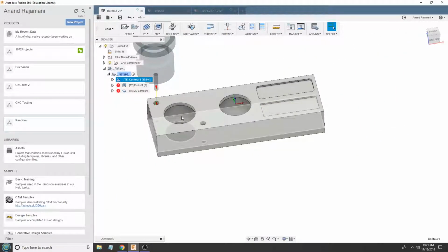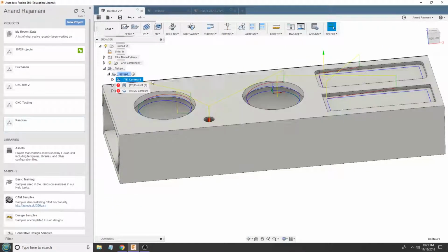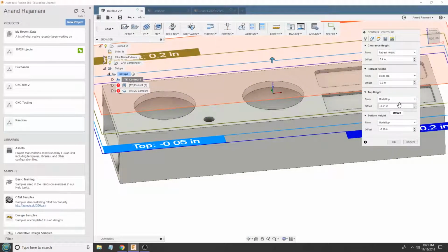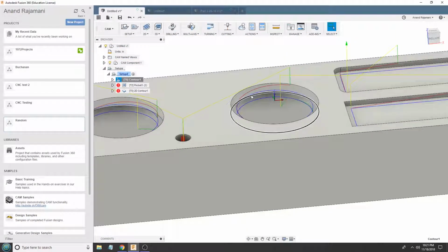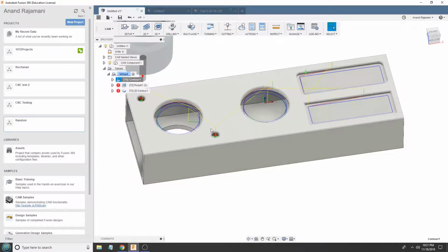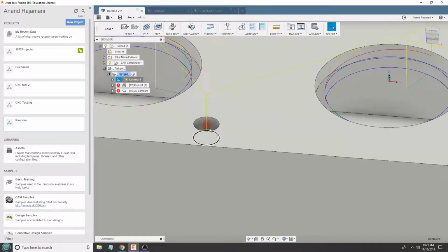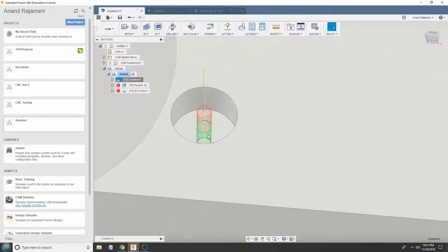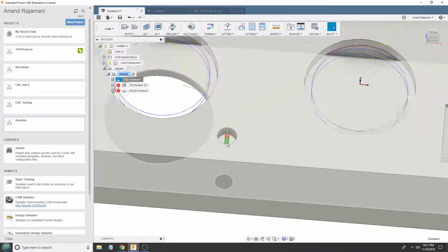Because I have bounding box selected because it's just a rectangle. And there you go. It'll just contour, no problemo. Totally fine. Might even want to do even more of an offset from the model top for this one, just to make sure I don't get that extra... I got it anyway. Sucks to be me. Still, it spirals down, gets that crisp helical motion, and leads out at the end in a helix. I don't know what to call that, but it doesn't matter. Point is, it gets done.